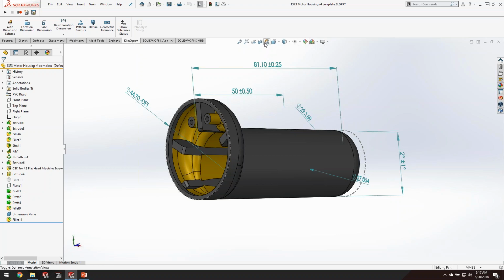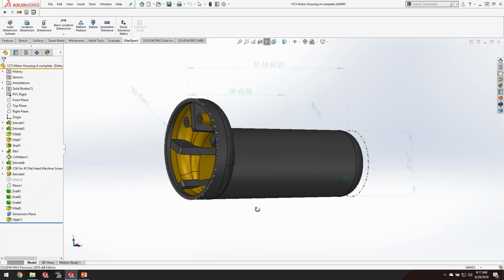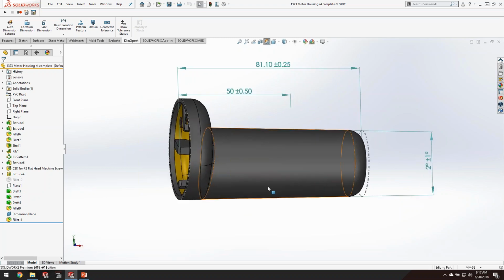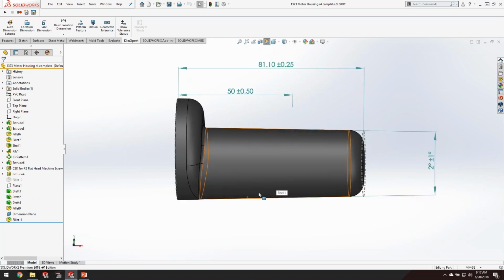And a couple of years ago, SolidWorks actually introduced a new button called Dynamic Annotation View. And what this does is it allows you to fully DimXpert your model, placing all the elements in different orientations, the relevant fields. And by turning this on, you're now able to slowly rotate the model. And as you come into a view that might have these critical dimensions actually located on them, they'll start to become apparent. So they're not overriding all of your user experience, right? So you're not just seeing a spider web of all the dimensions there.